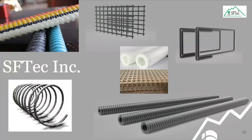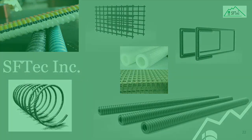Yes, you can use the glass fiber reinforced polymer mesh in this kind of slab, Hambro slabs. You can put it in by layers, but before putting the mortar, you have to put this mesh. I think 2 layers of the mesh should be required at the top and bottom.